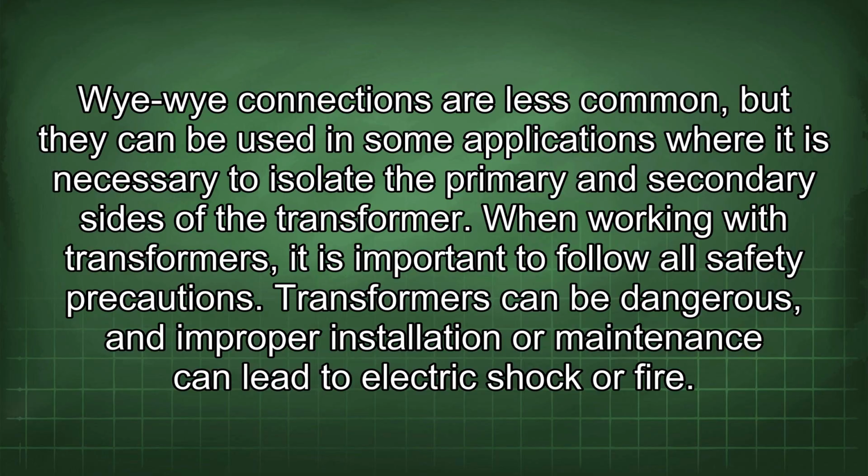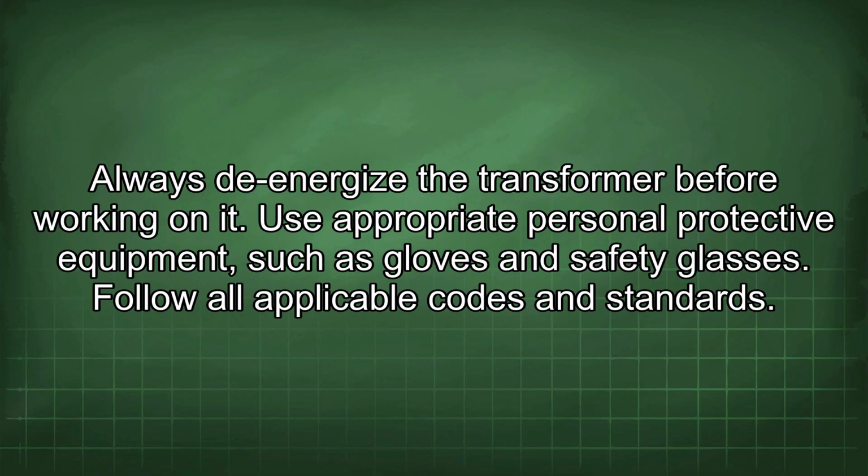When working with transformers, it is important to follow all safety precautions. Transformers can be dangerous, and improper installation or maintenance can lead to electric shock or fire. Always de-energize the transformer before working on it. Use appropriate personal protective equipment, such as gloves and safety glasses. Follow all applicable codes and standards.